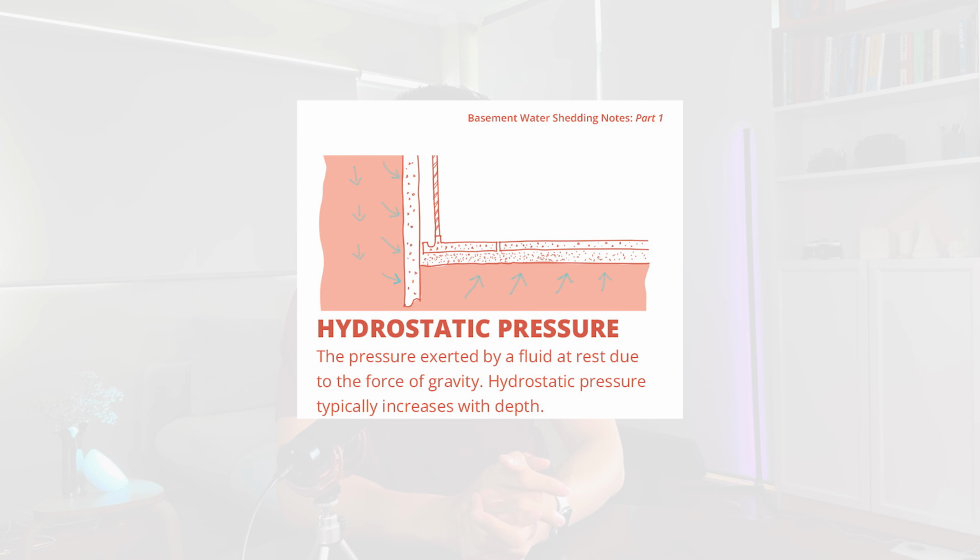Hydrostatic pressure is the pressure exerted by a fluid at rest due to the force of gravity. Hydrostatic pressure typically increases with depth. Most urban sites will require a pit and pump. A hydrogeologist's impact assessment will be able to determine if there will be minimum harm to adjacent sites for a pit and pump to be allowed.